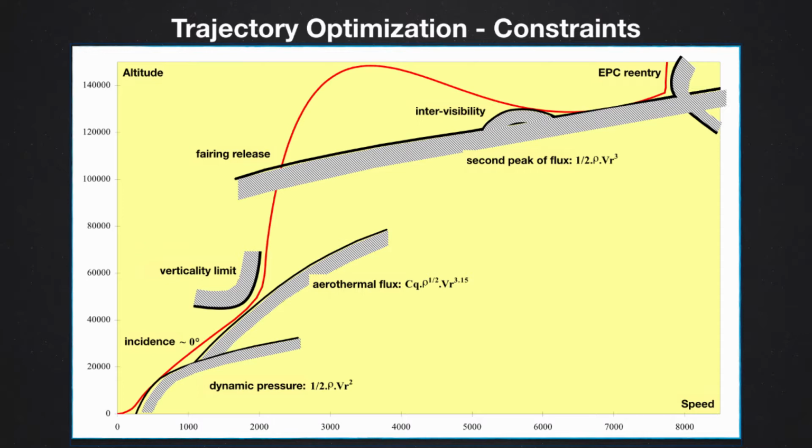And you don't want to go there, because if you go there, the aerodynamic force, which is proportional to the dynamic pressure, is going to be too high for the launcher, causing a structural issue, okay? So you want to fly quickly enough and go high in altitude to avoid having high pressure when your launcher starts going very quick.